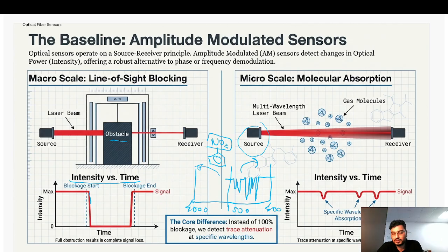Similarly, here it is mentioned about the basic plot, intensity versus time, where you can see how the light is absorbed. At the moment, the intensity is decreasing because the light is absorbed by the gas molecule, and based on that it can be sensed how much light intensity has been reduced once it interacts with the gas molecule, and how much is transmitted to the receiver.